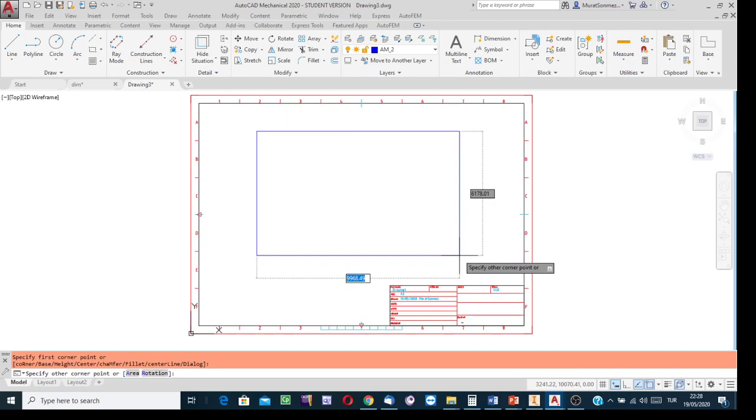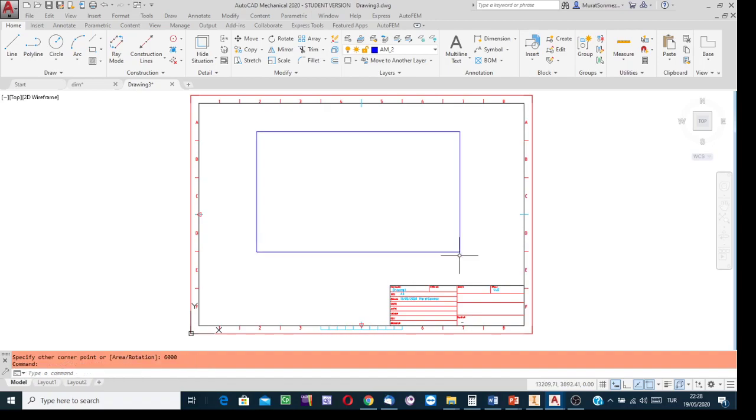Say that the main part of the plan view, create a rectangle and say that it is a plan view. Omit the other things, okay? The width of the little house is 10,000. Yes, into this box, what I am writing, 10,000. Sure, it is going to be recorded in millimeter. Tab key, and into the other box, write the depth of the house. It is, in this example, 6,000. In meter, 10 meters by 6 meters. But it is in millimeter, 1,000. Press enter. And then say that finish the plan view and it is time to show the dimensions.